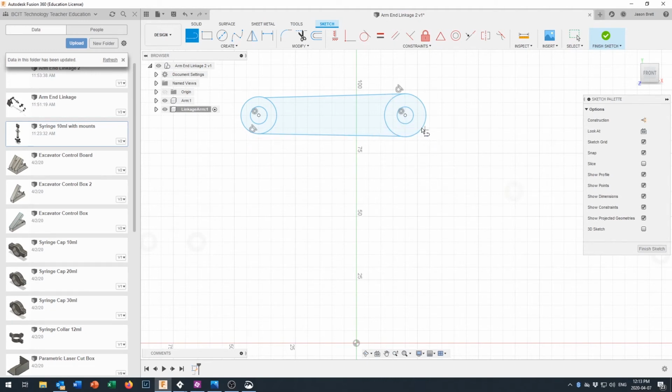We've got 2 concentric constraints, so those circles stay together with each other, but you can see we don't have tangent right over here. So pick up tangent and say the circle should be tangent to right there. You can see now we have a tangent constraint pop up in there. And the circle should be tangent to right there, and that pops up right in there. Now, it's possible that if you drew that line perfectly horizontal, there is a horizontal constraint that looks like that sitting right in the middle.